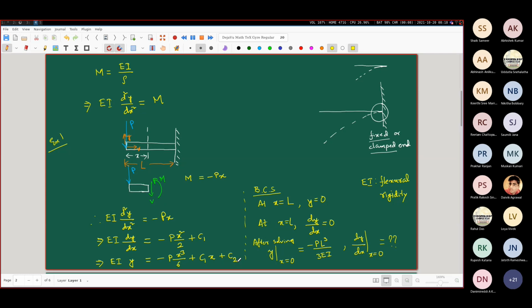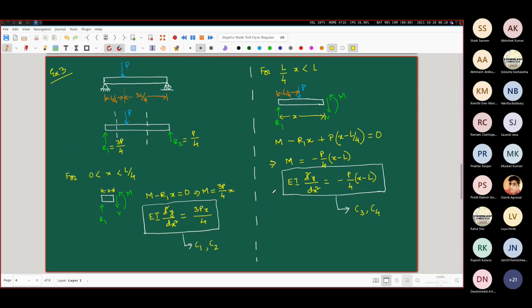Now we are again ending up with second order differential equations, but because we have two forms of the equation, mind you that we are still talking about the same beam, but two forms of the equation in two different regions. Correspondingly, we are ending up with four different constants of integration. So it would seem that we need four boundary conditions, because we have four unknown constants.